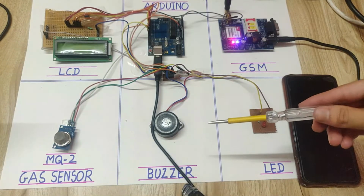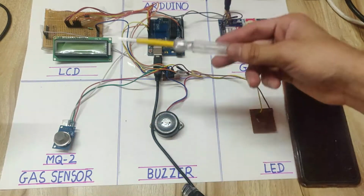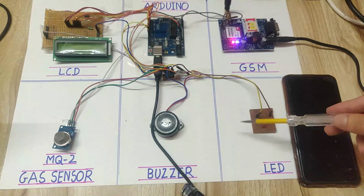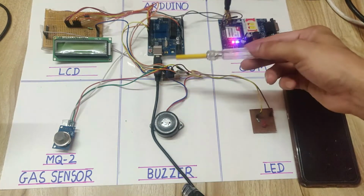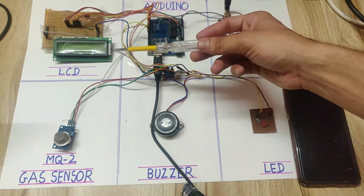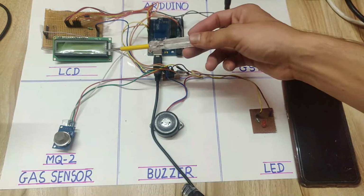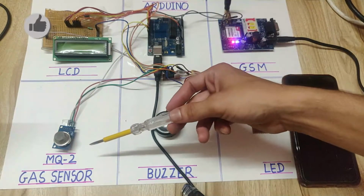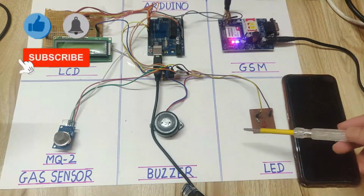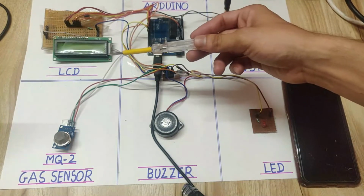As you can see on the screen, we have the Arduino, the buzzer, then the MQ2 sensor which detects the fire, then the LCD to display the message, and an LED for the status indication. Once I give the power to this Arduino, this LED will turn on. At the starting you will see the message fire detection system, that is our project name. Then fire is not detected by this MQ2 sensor, and this LED will turn off.